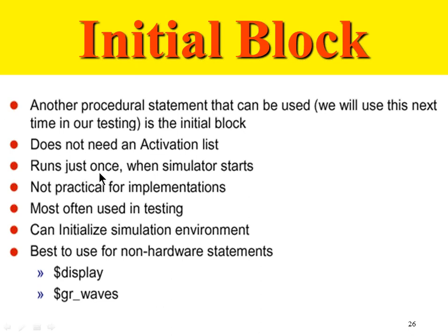So can you think about the initial block? Why would I need something like an initial block, which will run only once, not again? An initial block can have multiple statements, like an always block. It can have one or multiple statements, so I can include as much logic as I can inside the initial block. But the condition is, it will run only once when the simulator starts or when the design starts. Why would I need something like that in hardware?